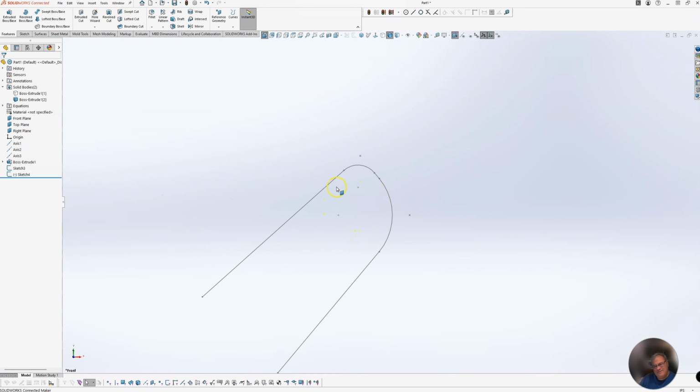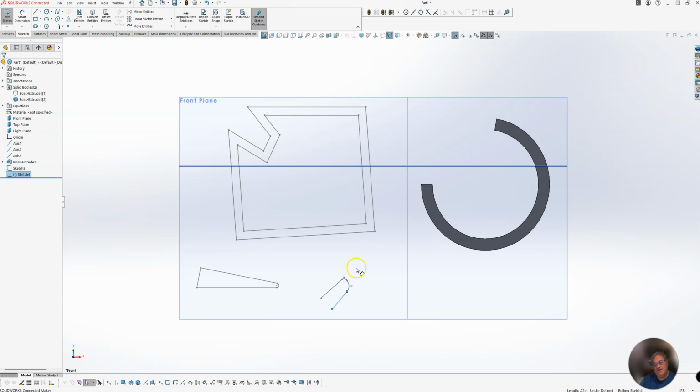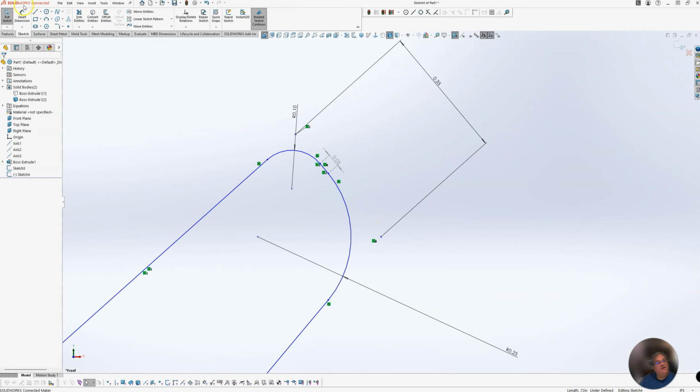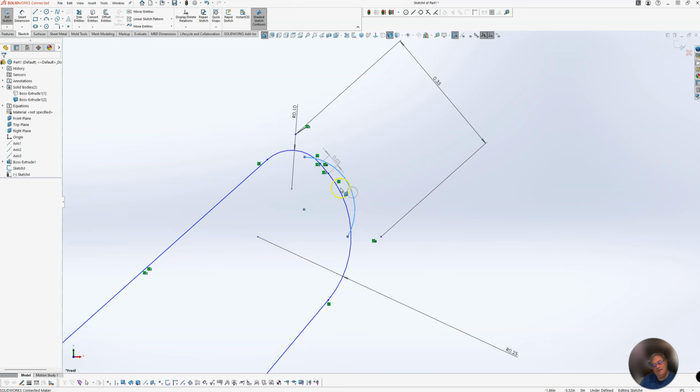So let's say you get into this situation where you've got this geometry and you want to do a full ring. How do we want to do it? Okay, we want to put another radius in this for whatever reason, just for the sake of argument. So let's do a 3-point arc, and we go here, here, and here.